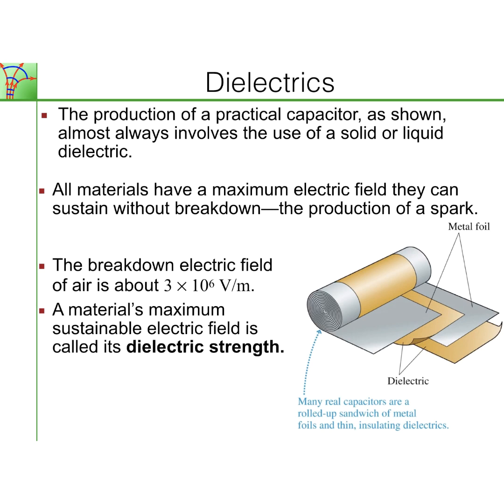And in the production of a capacitor, it's practical, right? You want some way to separate. If we have two sheets of metal that we want to use to make a capacitor, if you want a lot of area, you roll it up and you put something in between them and keep them separate. And if that dielectric also increases the capacitance, that's even better.